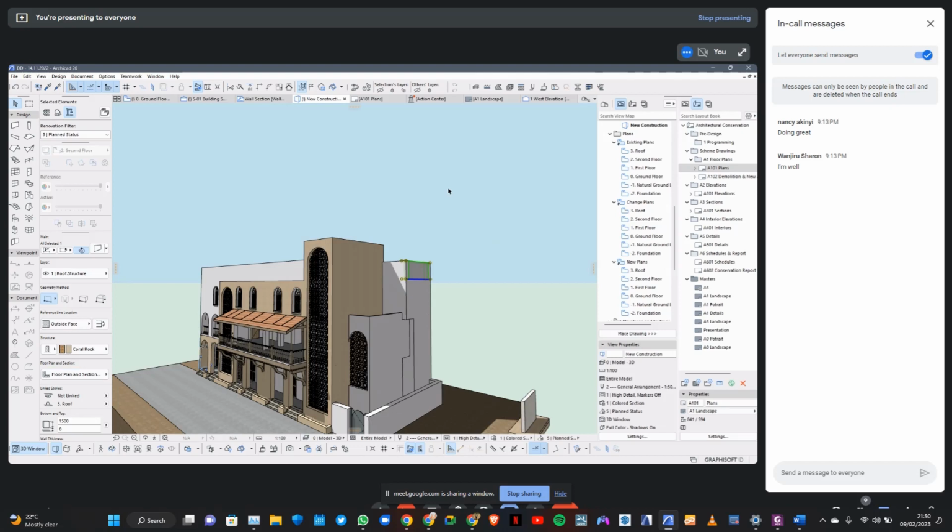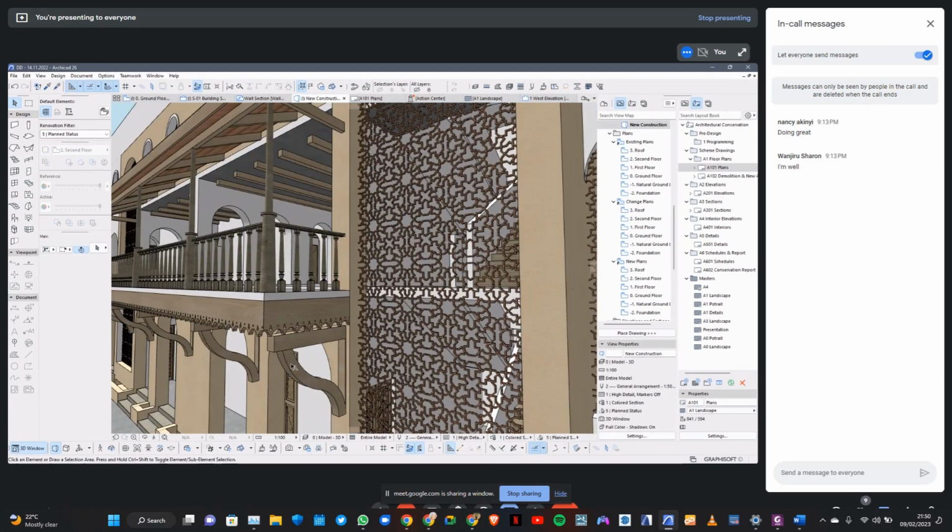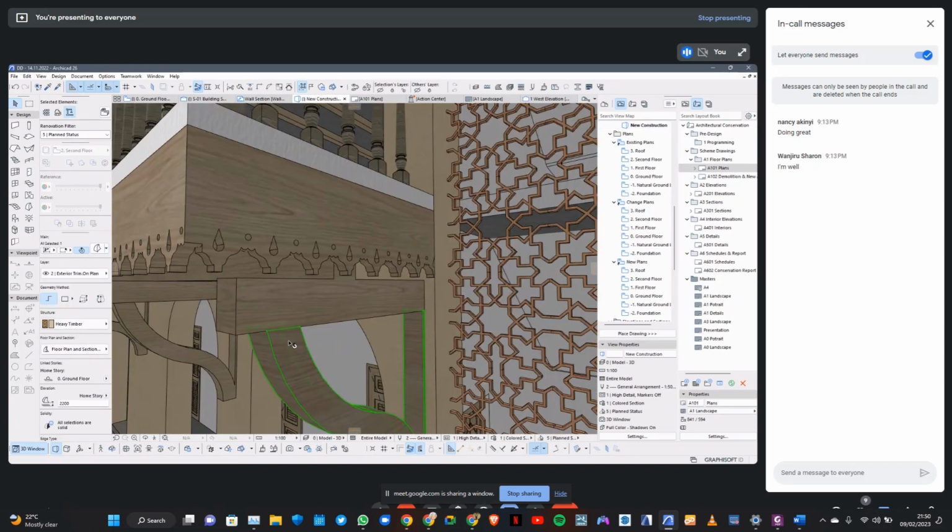If I create a surface override, it does not affect the building material, it just affects the element. But if I change the surface on the building material, every element using that building material will have that change, whether that override is on or off. But the override always has first preference. ArchiCAD gives preference to the overrides. Yeah. So now that's that on materials.